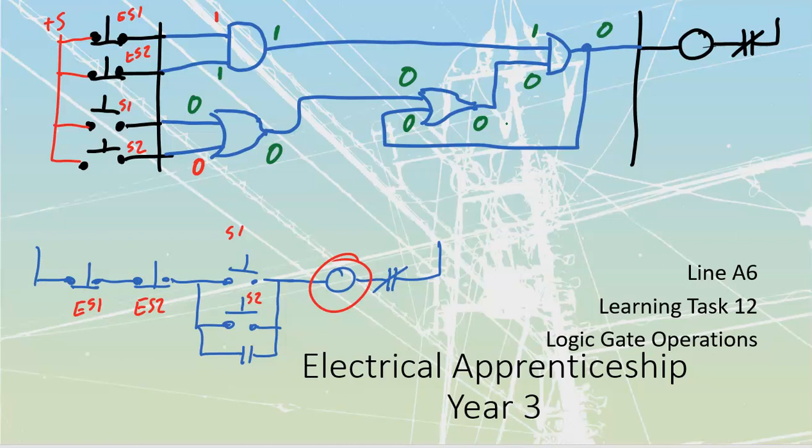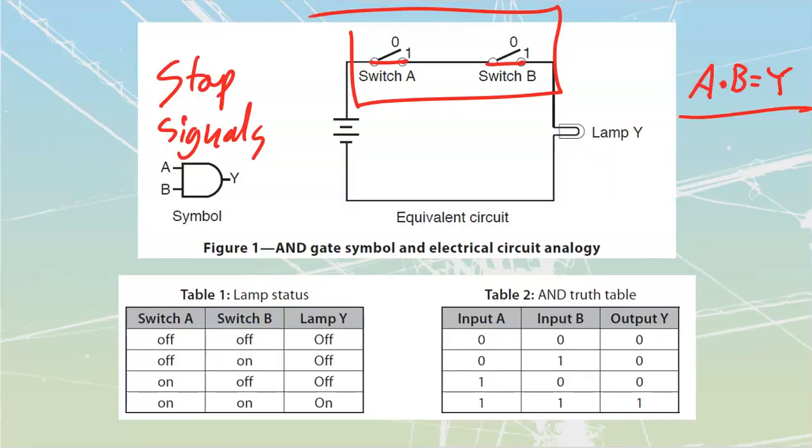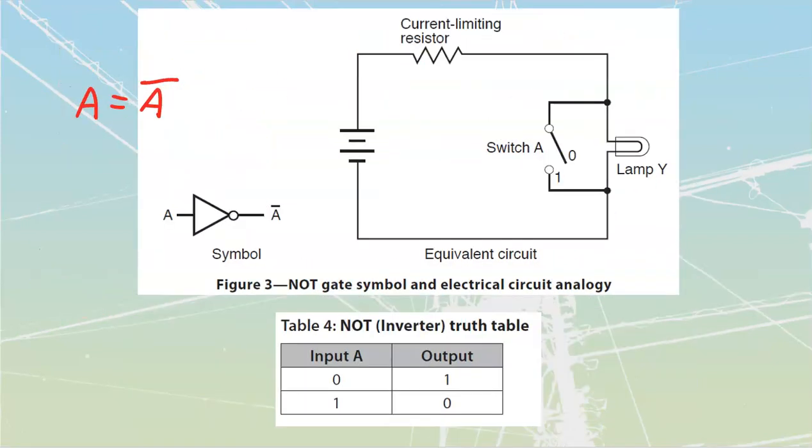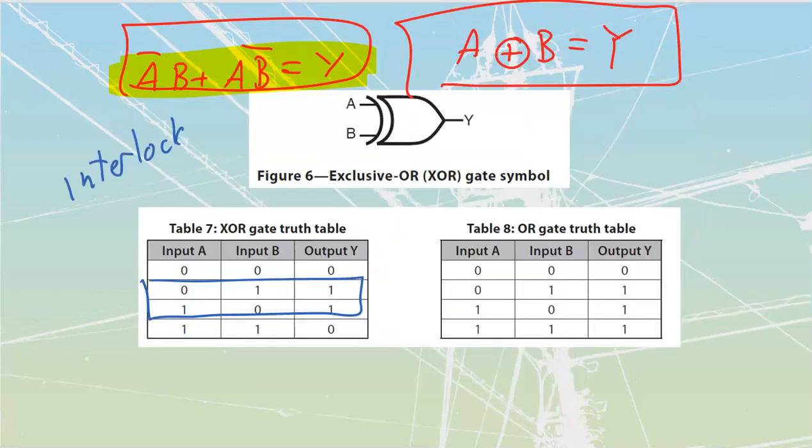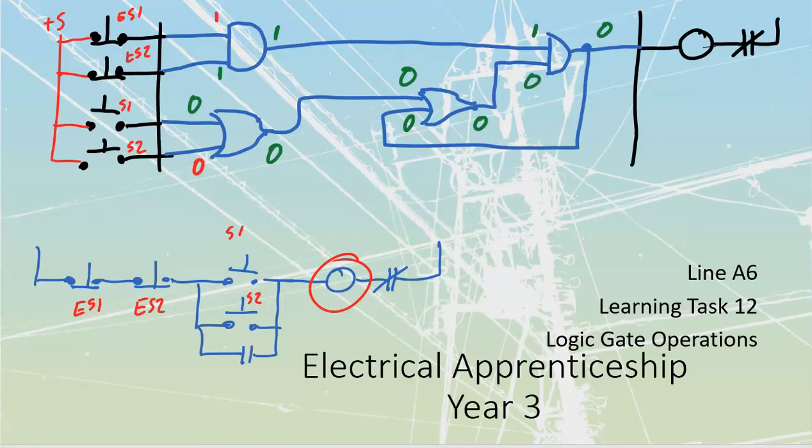This is where you're going to find applicability of all of these ANDs and ORs and NOTs and NANDs and NORs and XORs is going to be inside of programming. Okay? There is, under programmable logic controllers, a couple of main branches of programming. We have got our ladder logic, which is really old. It's really easy for us to go and read and understand. It's really hard to write, but it's still in a lot of older installations.